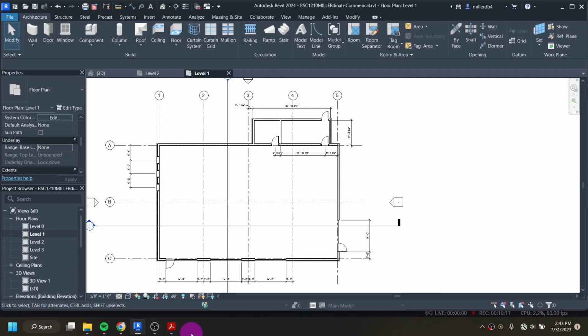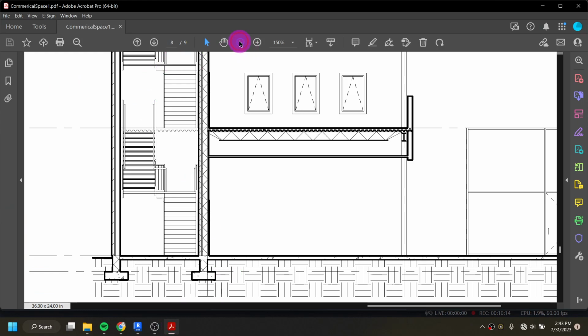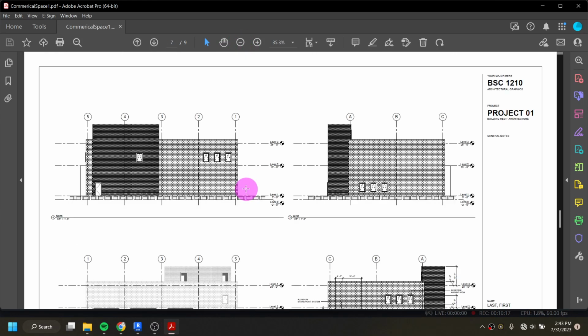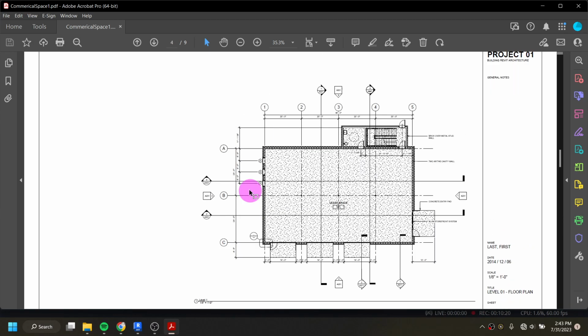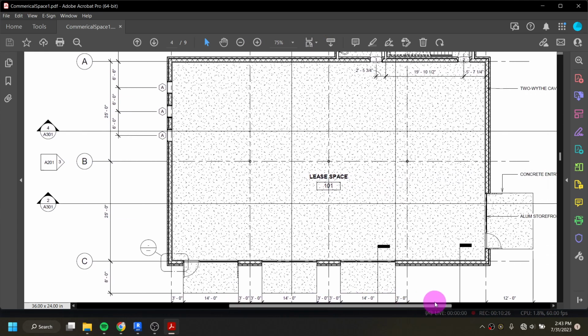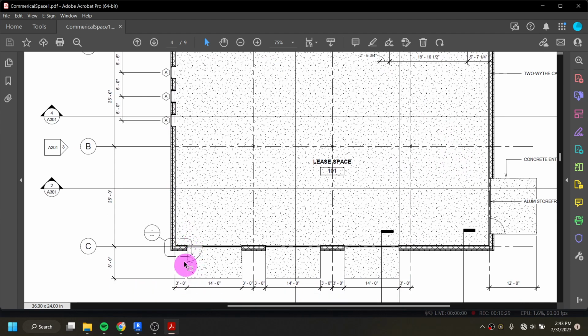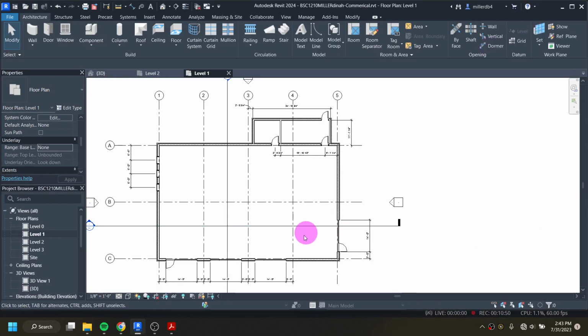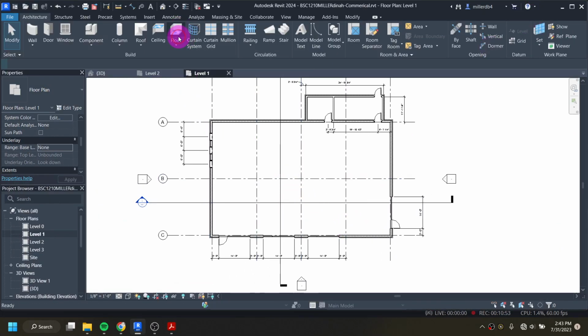And so from what we can see in this floor, if we go into our drawing here, let me just zoom out so I can scroll up a little bit faster. That's my roof. Okay. So this is all going to be modeled as just one floor, including these pads out here. They're going to come 8 feet out from that grid line, 14 foot over, 8 foot out, 14 foot over, 12 foot out on this side here, around where our grid line and our curtain wall is. So what I'm going to do then is go back into my floor tool.